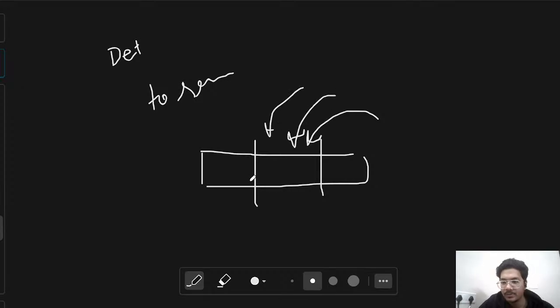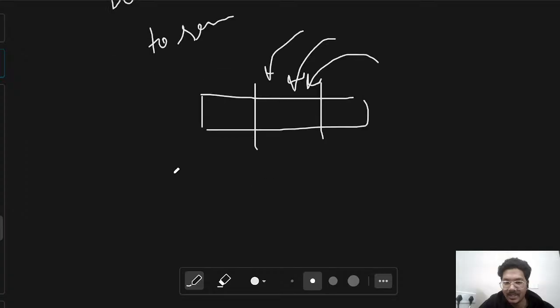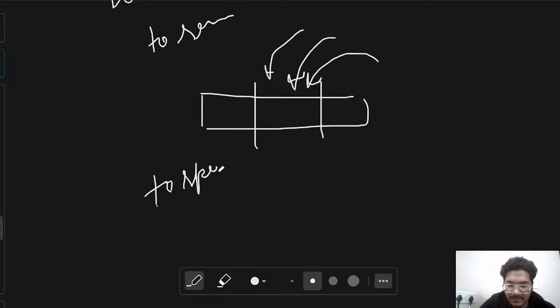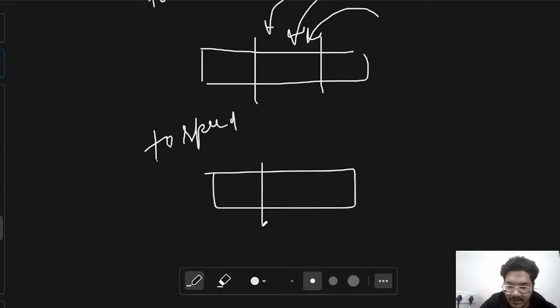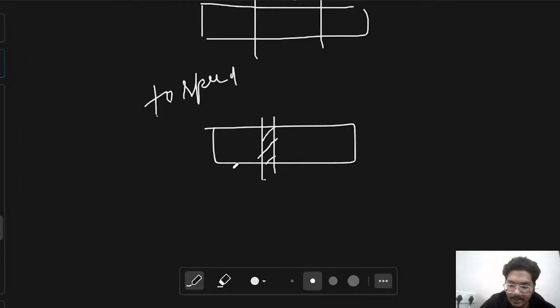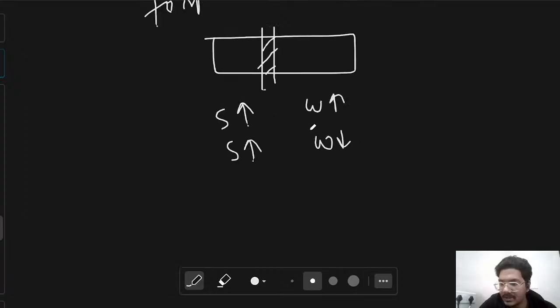To increase the speed, the depletion region must be shorter, so it reduces the drift time. That's why the depletion region is shorter. But if we want to increase the sensitivity, then the diode has to trade off between these two things to optimize the device performance.